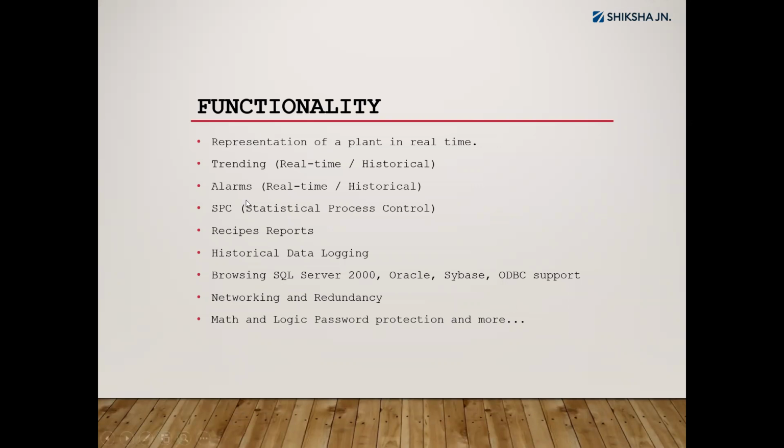Then alarming conditions are there. Alarming is just like this: I have set some particular limits for my process. Whenever the steam pressure exceeds a certain limit, I want an alarm to be generated. Generally in the field, the alarm is generated using a light or some sound. Suddenly the sound will turn on, suddenly the siren will go high. Why? Because it has crossed those limits. Whichever specified values or limits you have set for any process or parameter, you want to safeguard your machine so that it should not increase or decrease beyond that point. For that purpose, we generate alarms.